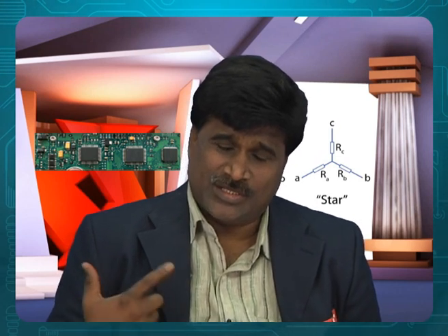We got the Ebers-Moll model, basically to understand how a transistor behaves like a switch in the forward mode, saturation mode and cutoff mode, and why saturation mode is called the on switch, because a lot of current is there, and why cutoff is called the off switch, because no current is there. At the most it depends on reverse saturation current.